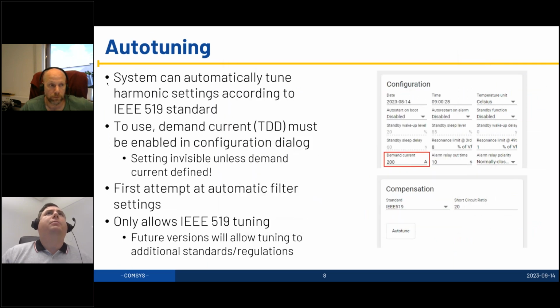So then we have the next question on the auto tuning. Do you need to set up mixed control compensation before performing the auto tuning, or will the auto tune sort out the mixed compensation as well if that is needed? I would run the auto tuning for the current control first, and then I would modify to the mixed control type you would want after that. So the auto tune is not saying directly, okay, here we need to adjust impedance control. Correct. Okay, awesome.